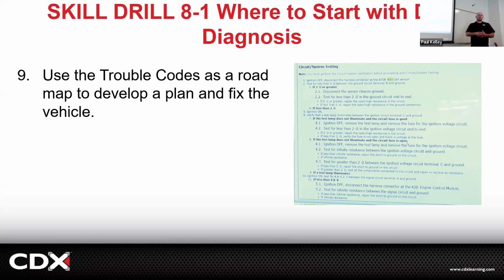If you've never done a compression test, you're probably not going to be able to diagnose that car. But if you've done a compression test, you can do the compression test. You can interpret if it was good or bad. This will give you your next steps. And then you'll get to the bottom and it'll be like, after your leakage test, did air come out of the intake or the exhaust or the radiator or whatever? And you'd be like, yeah, air came out of the radiator. And it would say, most likely it's a blown head gasket, but also check the head. That's how this troubleshooting works.